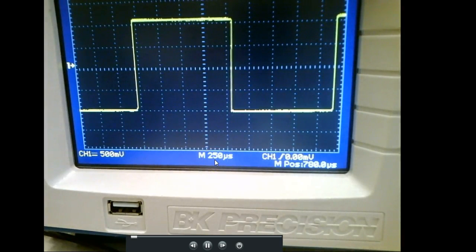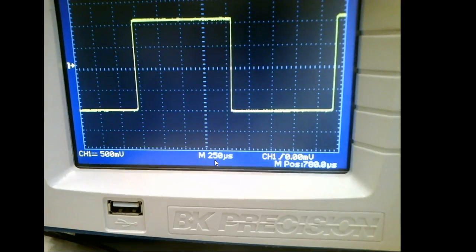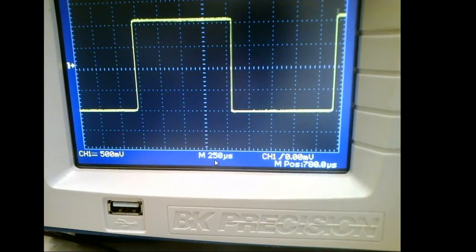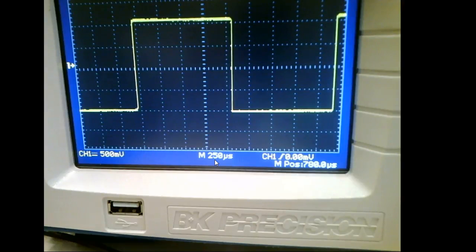Just about all scopes go in 1s, 2s, or 5s. This one has this 250, which screws me up, 2.5. But all your other scopes go in 1s, 2s, or 5s. And how many of y'all can count in 1s, 2s, or 5s? Every one of you learned how to count in 1s, 2s, and 5s in elementary school, right? So I know it's 500 millivolts per division, so I'm counting in 5s, right?